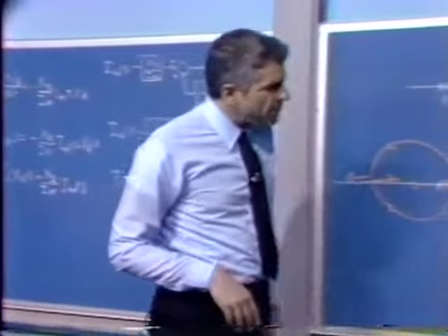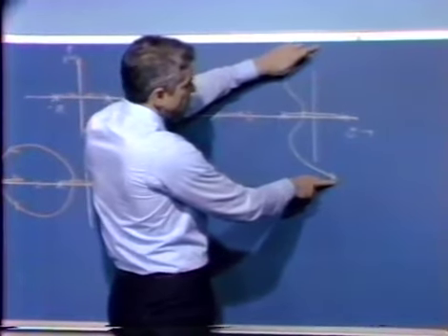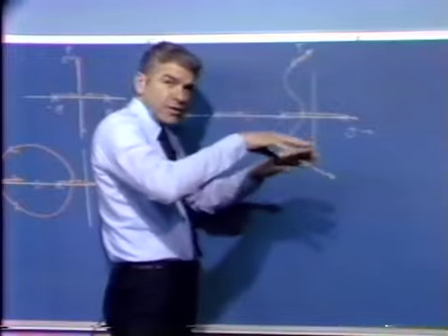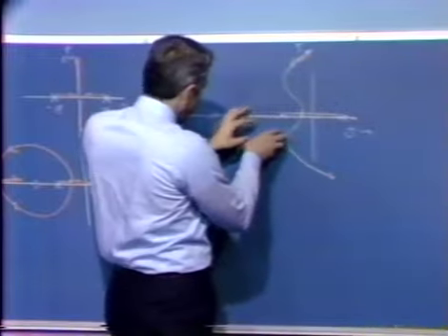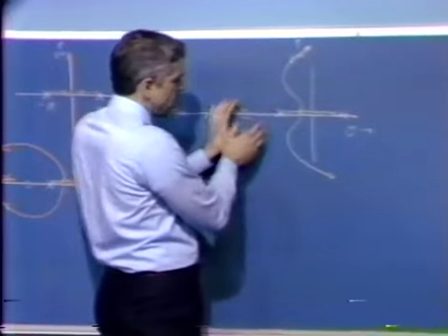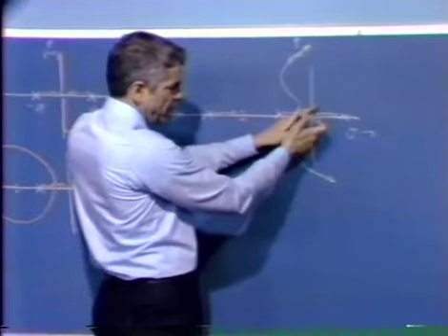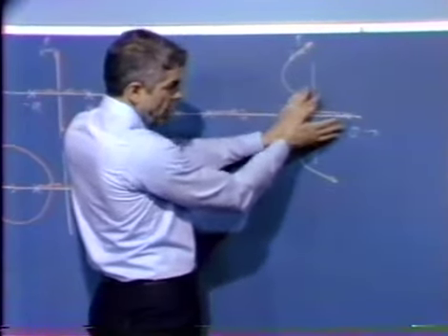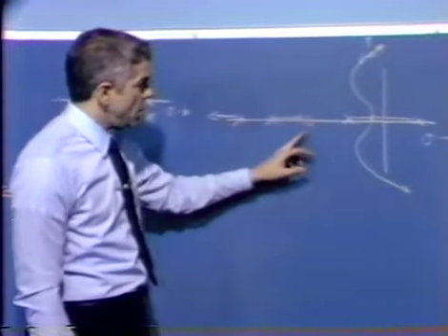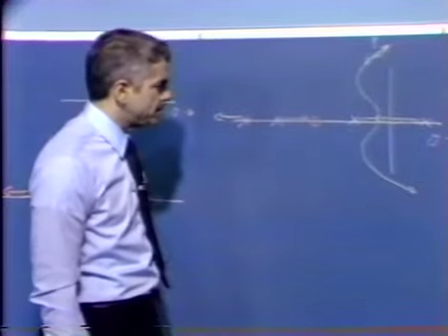And that corresponds to the case where either we have too much A naught, so that we have closed loop poles out here because we have an oscillation, or we have the zero improperly located, and if the zero were improperly located, these poles might never get into the left half plane. They might branch off the axis while they were still in the right half plane, and so that probably corresponds to the wrong location for the zero or too much A naught.